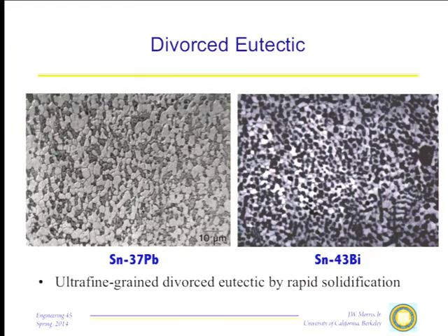They're unstable microstructures. So you'd like to get more equiaxed microstructures in solids. And the way that you can do that is to dramatically increase the cooling rate. If you dramatically increase the cooling rate, this happens kind of automatically in many soldering operations in microelectronics, because your soldering bump is 50, 100 microns in size. And you just drop a 50-micron liquid onto a cold surface, it's going to solidify pretty quick. So you can get it naturally in many solders.